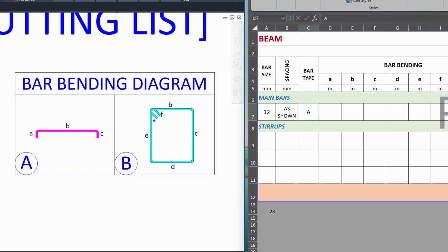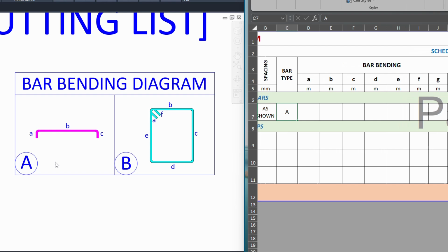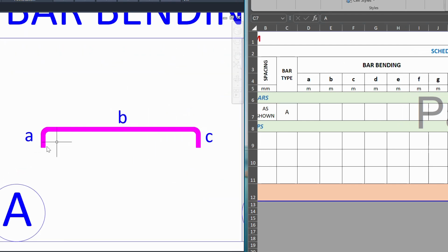So now we have to start on how we bend our RSB. So this is how we bend it. From support, the whole stretch of the beam, and then the other support. We bend it, it's hooked, and at the support here also. So we designated it as small letter A, B, and C. It means that here we need the length or the measurement of small letter A in meters. Remember that, or check here what the unit is. It's in meters, so ABC.